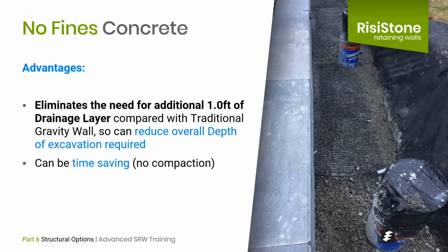There are a couple of main advantages to no-fines concrete. First, the fact that it eliminates the need for the additional 1 foot of drainage behind the wall, as we see with traditional gravity walls, means the overall depth of excavation required is 1 foot less. This might not seem like a lot, but in situations where property lines and tight spaces are present, this can be the difference between fitting into a site and not. Second, because the no-fines mix does not require compaction, the installation can be significantly faster than other options.